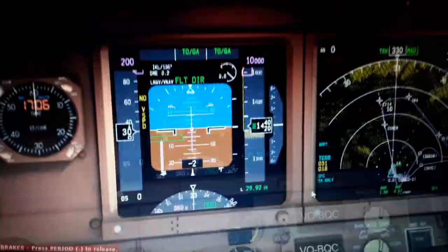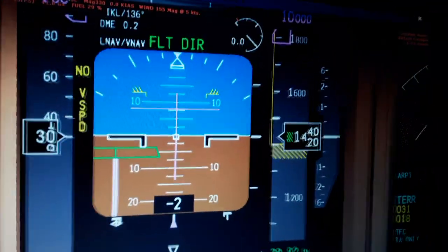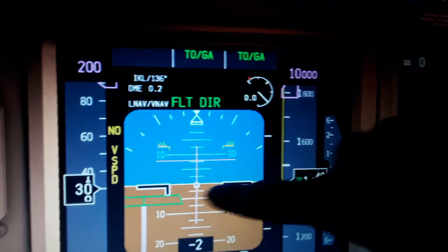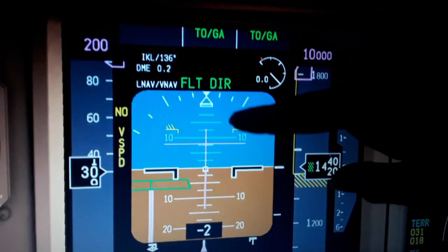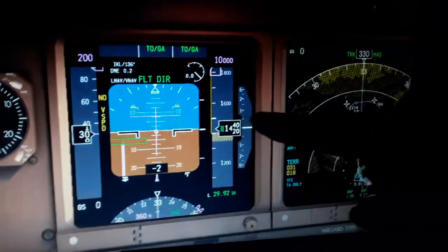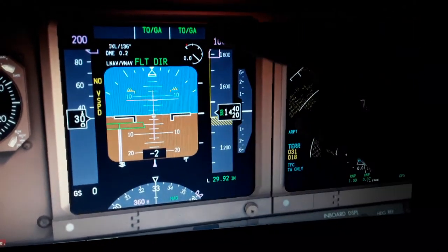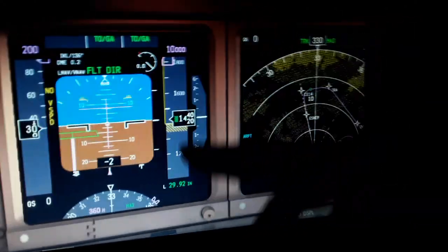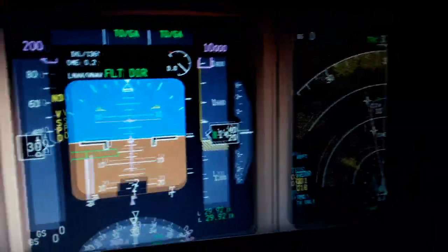So we have the pitch ladder in decrease here, the artificial horizon with the attitude indicator, like 2.5, 5, 7.5, 10 degrees, pitch up, 12.5, 15, 17.5, 20, 30. So you have pitch up and pitch down. We have the barometric pressure above the sea level, the barometric pressure of the outside atmosphere, the altitude selected from the autopilot flight director system panel, the takeoff ground modes are.